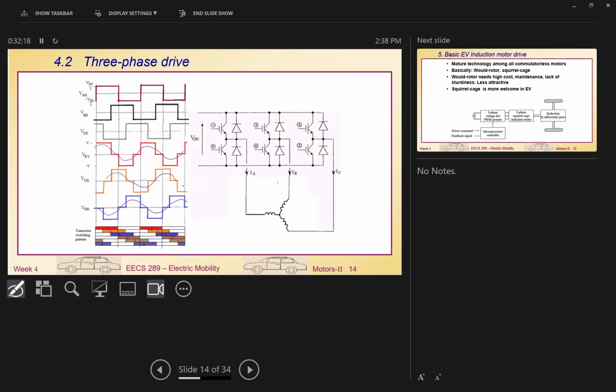When we use an inverter, the pulse pattern that comes out is this kind of chopping waveform, not a sine wave, but that is good enough for us to drive a motor. We don't really need to put a filter first. In theory, you may think, I'd like a filter to turn all the chopping waveform into a sine wave before it goes to the motor. That would be perfect, but we don't need to do that. Why? To reduce cost. Yes, of course, reducing cost is a really good answer. But when you tell your boss you just reduced cost and don't care about sine wave performance, it's still not a good answer, though it's good enough.